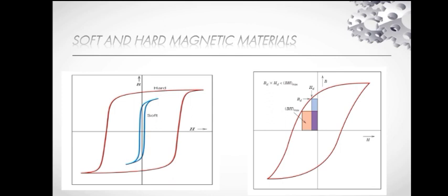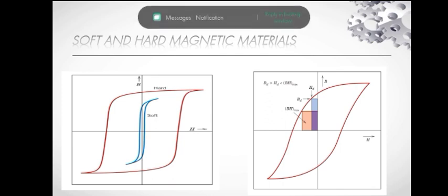The two most important characteristics relative to application for this material are the coercivity and what is termed the energy product, designated as (BH)max. This energy product corresponds to the area of the largest BH rectangle, as shown in the figure, that can be constructed within the second quadrant of the hysteresis curve.